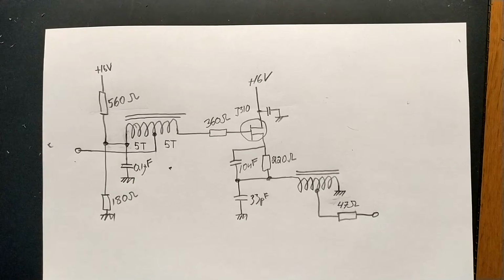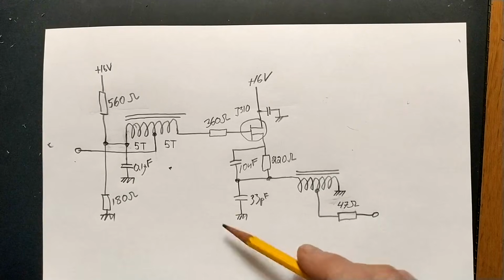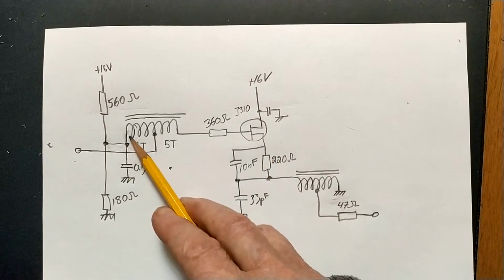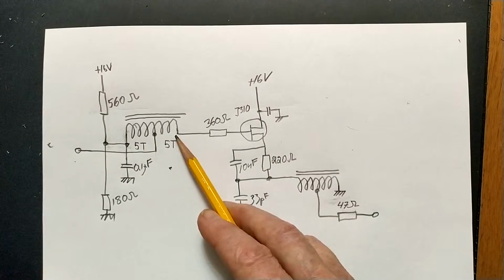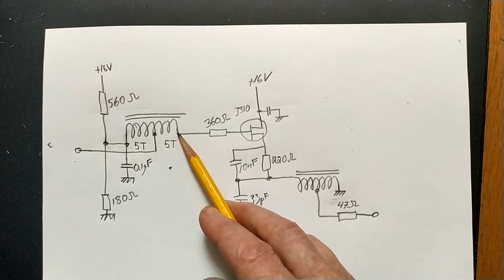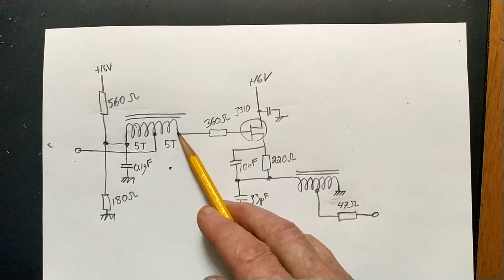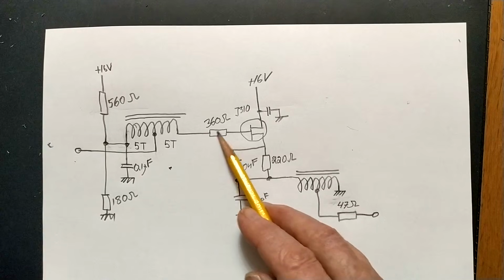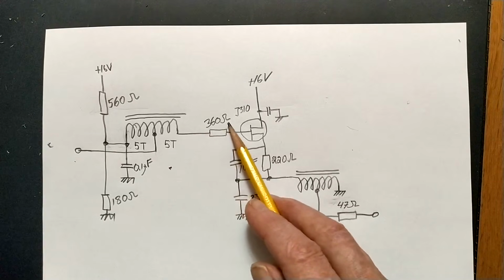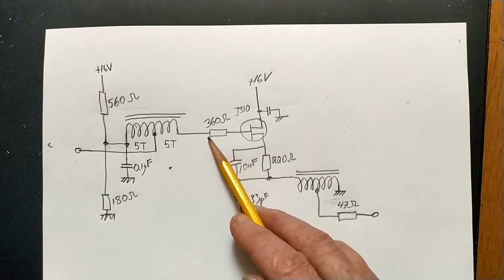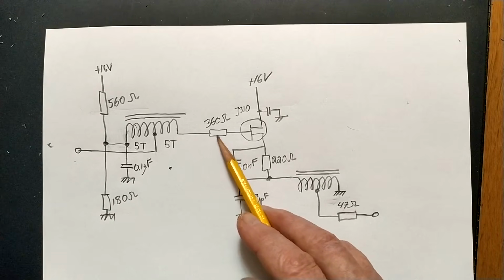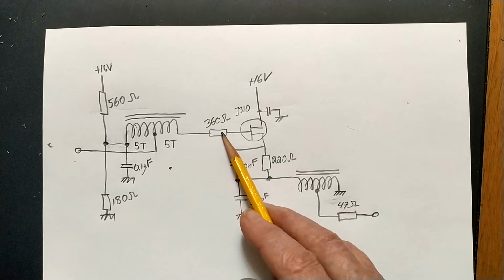This is the first amplifier I'm trying. It's a source follower with a single J310. First, a step-up transformer to increase the voltage by a factor of 2 means the impedance a factor of 4. This resistor is to kill oscillations at about 70 MHz. The impedance is so high so I don't think the loss through 360 ohms matters at the signal frequency, but I will check that later on. I could find some better way of killing the oscillations.